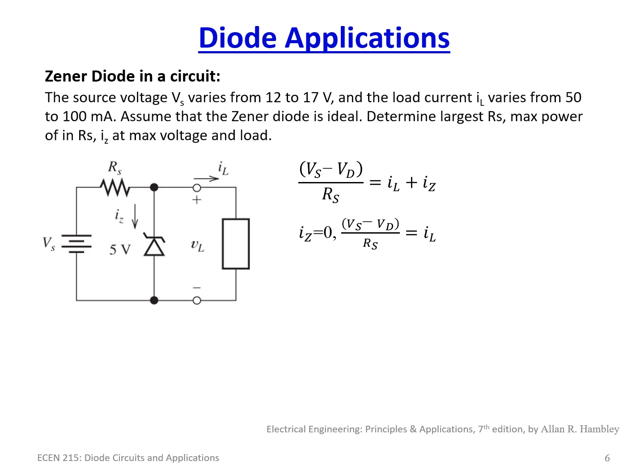So, that means that, why IZ equal to 0? Well, that means that all of the current is going to the load. That would truly be the case for maximum load current, which also would be the point of maximum load power, because remember, power of the load is equal to I squared R, or if this is an impedance, of course, we'd be dealing with Z. But we're particularly looking at resistive loads here.